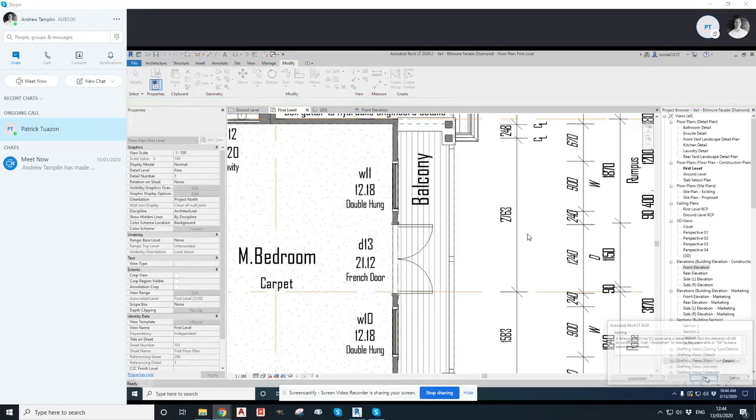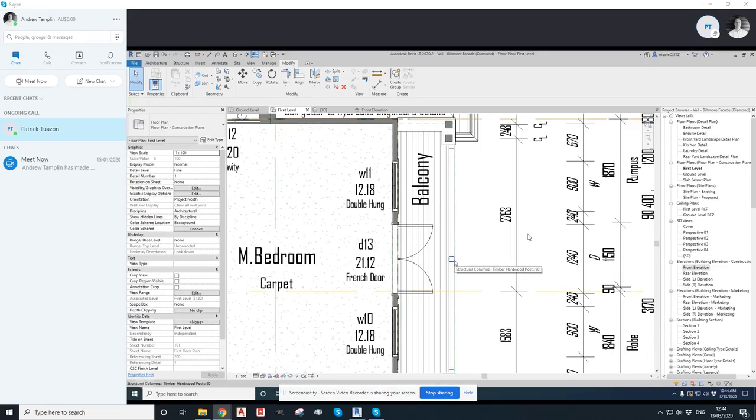Do you know why we just did that? No. So just before, you know how you press the tick button once you finish what you're drawing? Because we kept that dimension there, it moved the middle post, because we had already set the dimension to be equal spacing.